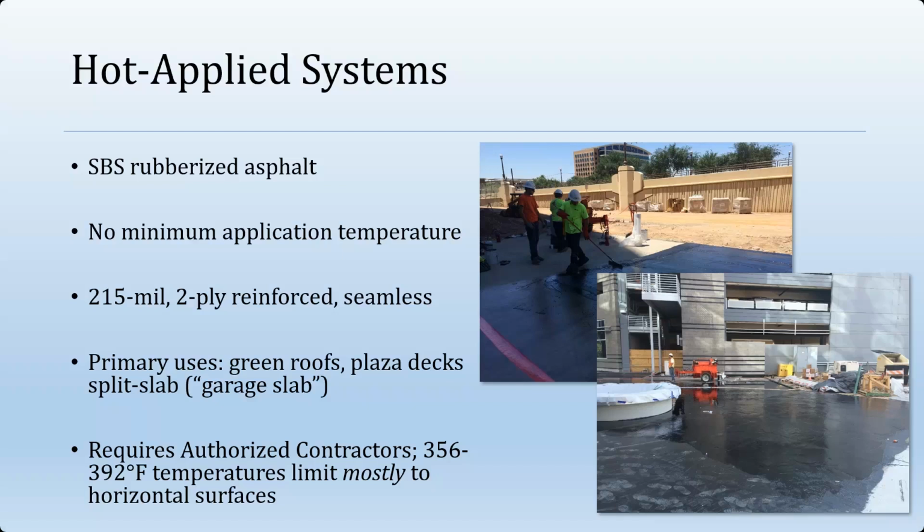One of the big points of contention is the concrete they're applied to. We can certainly apply this over cement board and plywood, but the concrete has to be aged. Typically, we specify 28 days, 14 days the absolute minimum. Lightweight structural concrete is possible, and I'm emphasizing the word structural, but it requires a minimum 60-day cure time. Lightweight non-structural concrete is certainly off the table. We simply can't. It's too friable a material to gain any type of good mechanical and adhesive bond.